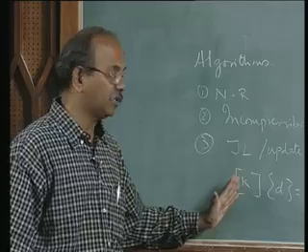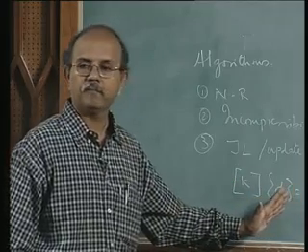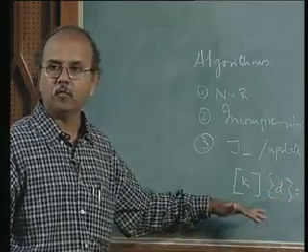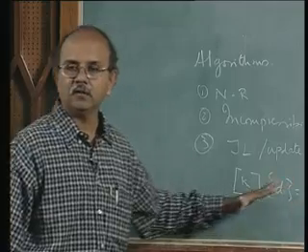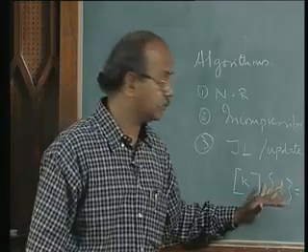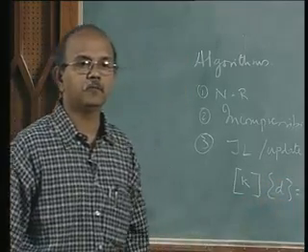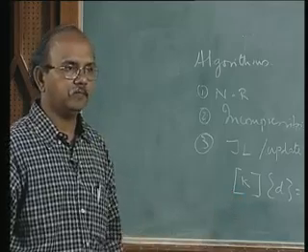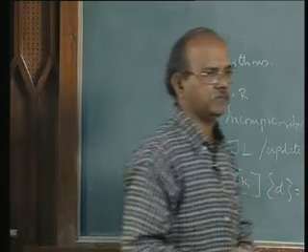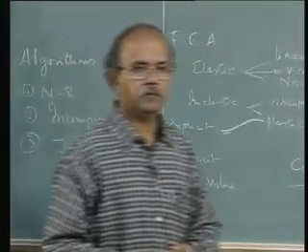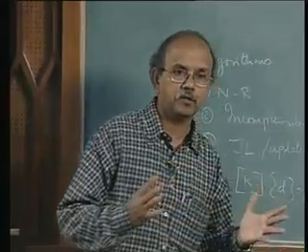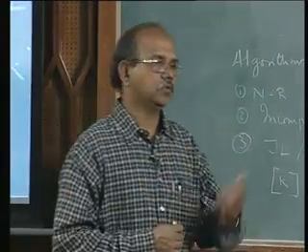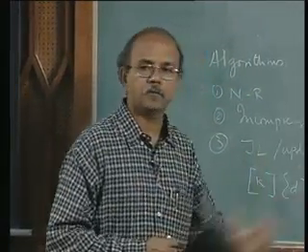So, K is not a function of D. You solve the problem only once, you apply the load, you use the K, solve this equation for D, by whatever be the procedure, right from preconditioned conjugate gradient or Gauss elimination, whatever it is, you solve this problem.